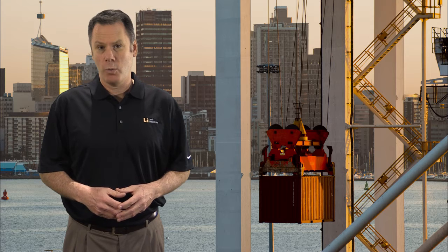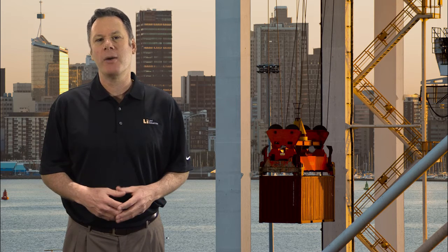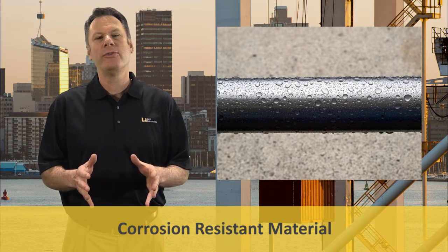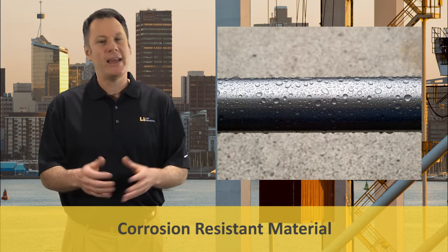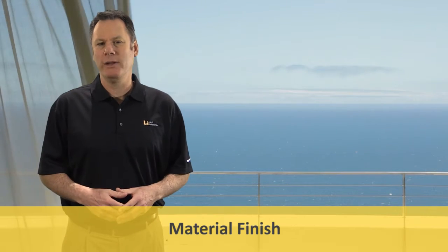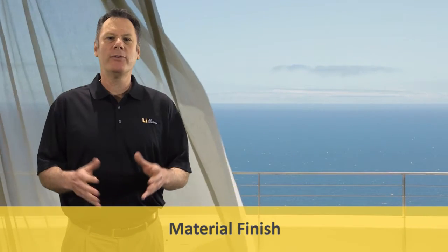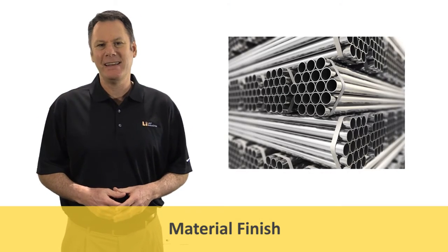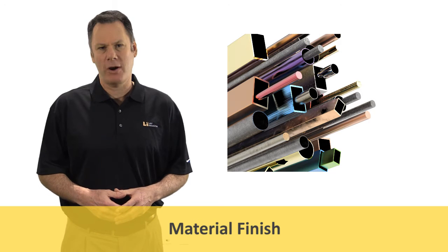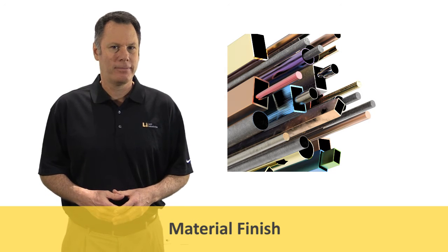Salty air creates a harsh environment for railings. Railings in locations near saltwater or adjacent to a marine environment, such as a bay or ocean, should use a corrosion-resistant material both indoors and outdoors. The material finish must also be appropriately evaluated. We'll discuss the durability of specific alloys, such as stainless steel 316 and anodized aluminum, which are commonly used in these environments later in this course.